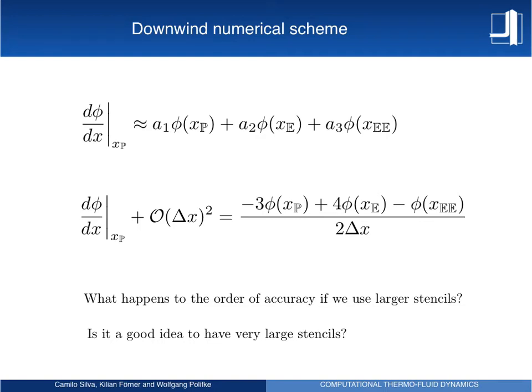So you will see that for diffusive problems like the one given by the heat equation, you don't really need to have very high order of accuracies. You can have very reasonable results, very accurate results actually, with second and third order of accuracy without trouble. However, there are cases when you want to explore, for example, propagation of acoustic waves.